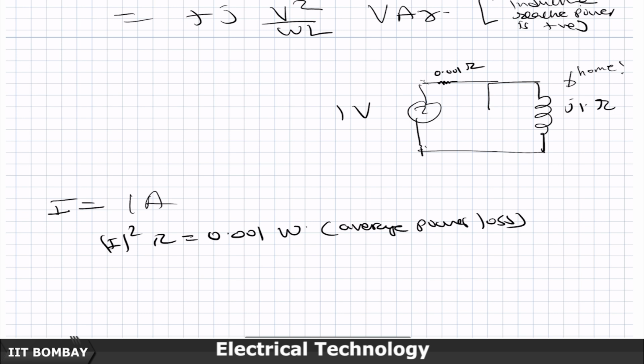This goes as societal loss, is it not? If you look at your billing, it is for the energy which you consumed. Now, you are not consuming any energy, because whatever comes in one quarter is returned in the next quarter. So, it is a double frequency oscillation in which net work done is 0. So, your energy meter is going to say that you are not consuming any units.